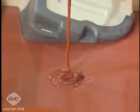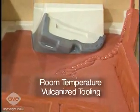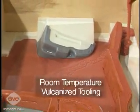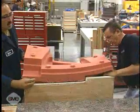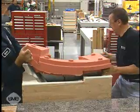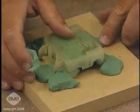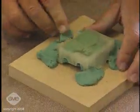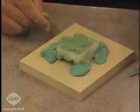A rapid means of producing soft tooling for low-pressure molding involves the use of room temperature vulcanized, or RTV, silicone materials. These RTV silicones are the preferred materials since they do not require special equipment for curing. In general, RTV tooling production begins by using a prepared rapid prototyped model as a pattern.